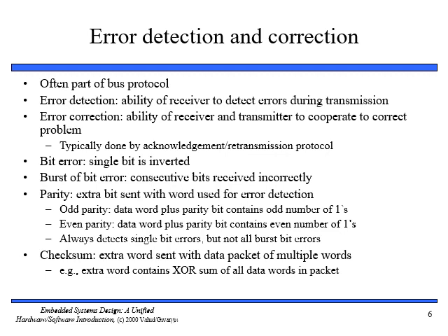Before I start error detection and correction, there are a few points about the previous slide. RF transmitters and receivers must agree on a specific frequency in order to send and receive. Using frequency hopping, it is possible for the transmitter and receiver to communicate while constantly changing the transmission frequency. Of course, both devices must have a common understanding of the sequence of frequency hops. Frequency hopping allows more devices to share a fixed set of frequencies and is commonly used in wireless communication protocols designed for networks of computers and other electronic devices.